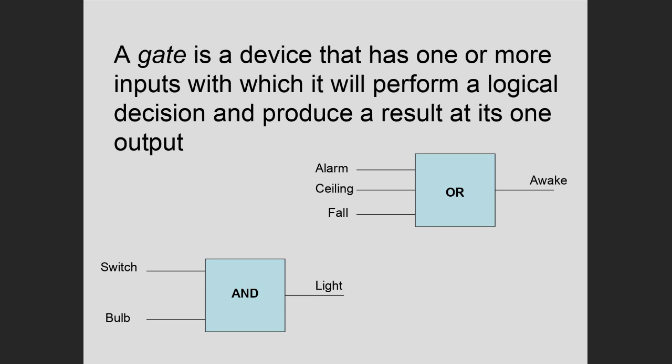And I can have a 2-input AND gate. I can have a 3-input. I can have as many inputs as I want. It's actually a circuit. You can actually purchase an integrated circuit, a chip, IC chip, with these AND gates on it, AND logic. So a gate is just an electrical circuit, a solid state device that mimics those physical circuits that we talked about with switches. And so for every logic function, the basic functions, the AND, OR, NOT, and the other functions we're going to talk about, you have these gates.